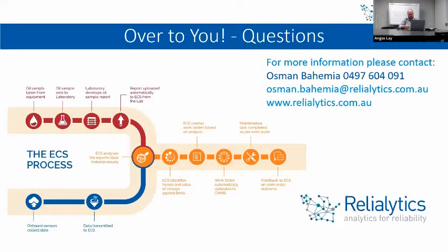So yeah, handwritten notes are fantastic feedback from the guys putting it on the work orders. You need to have a process to capture that and get it into your CMS system against that work order. Specifically when you're doing defect elimination, that information is critical to understand whether or not what was recommended has fixed the problem, or if it hasn't, what we need to do next to rectify that problem.